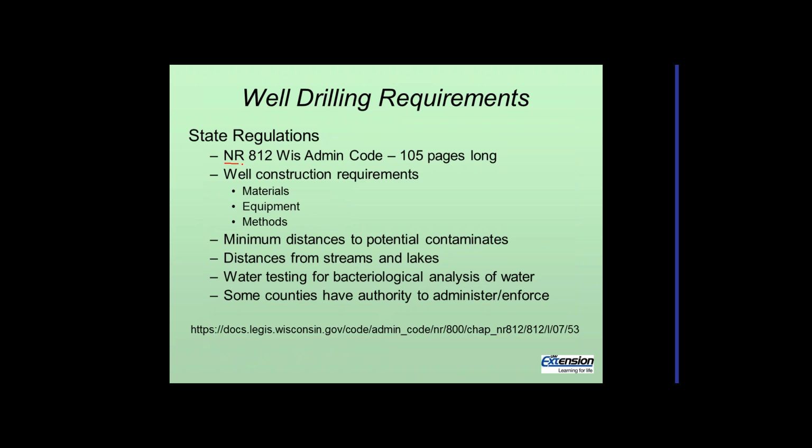For drilling wells, we have state requirements. Basically, it's NR 812, Wisconsin Administrative Code. It covers materials, equipment, and methods for drilling wells. It also has minimum distances to potential contaminants, minimum distances from wells, minimum distances from streams and lakes, and usually requires some bacteriological testing and analysis for the water.